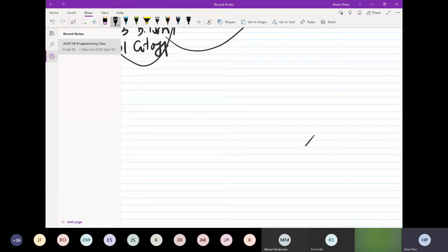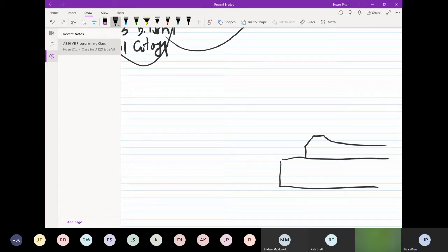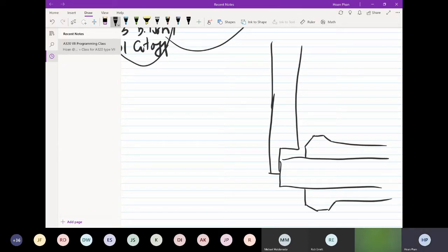So very simple like this. We have the main spindle with the guy pushing like this, and it's carrying the material. And then in this case, I said we're going to use the left hand cutout. So this side of the cutout is going to be Z0. And now we have the material sticking out like this right here. It's sticking out this much.